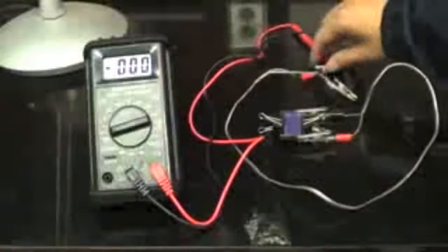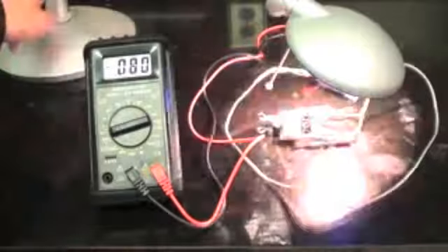Using alligator clips, attach ends to the exposed conductive sides of the offset glass. The titanium dioxide side is the negative side, while the carbon soot is the positive side. Connect the assembly to an appropriate meter and hit it with a very bright light. And look at that! Our crude solar cell is making a very small amount of current, and it's definitely doing it in response to the lamp. It's really tiny though, about 100 microamps. Now let's check the voltage, also pathetically small at 100 microvolts. A good commercial solar cell is thousands of times more powerful. But this is a fairly crude cell, and there are lots of improvements that can be made.